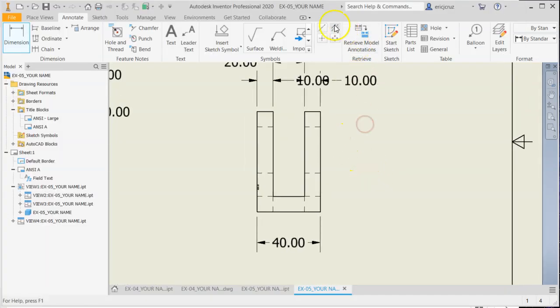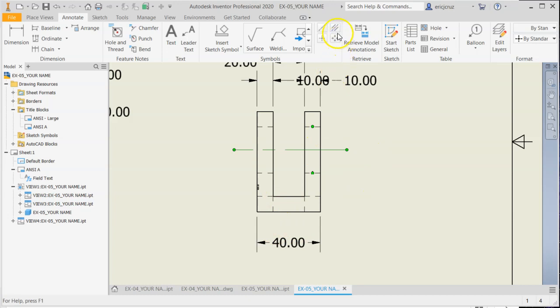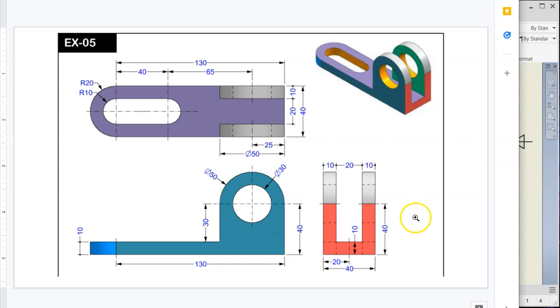Oh, we need to add another center line between here and here. Double tapping escape and extending this line out. We'll make this, again, we'll go in and make it nicer. Just keep on track with me. We have another hole here for that slot. I don't think we need this 10 right here. That's redundant. We already know it's a thickness of 10 here.